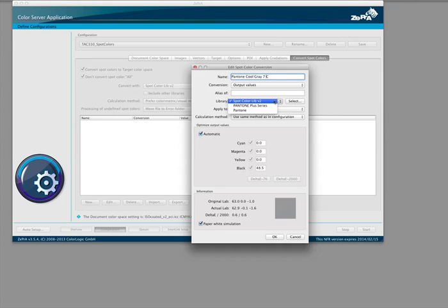If a spot color is found from ZePrA, it will tell you in which library this spot color is available. So that means if you have the spot color put into different libraries with the same name, those libraries will be listed here. We want to convert with this library. You can say what kind of conversion you want to do. You can do the conversion with defined output values. This is the default setting, or with the alternate color space just for compatibility reasons. Or you can even say, I don't want to convert that spot color at all. It shall stay in my document.